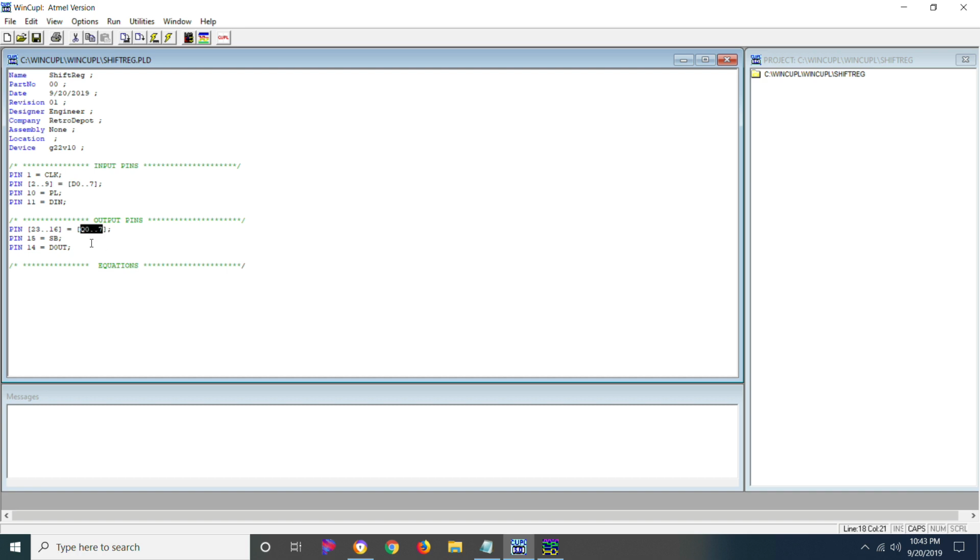Even if you decided not to do it that way and you were just going to be cycling this by hand, for example, to emulate a 74LS166 or a 74LS165, you could simply use the chip select as both a writing mechanism and a clocking mechanism. That's a pretty easy way of going about it. So we're not going to concern ourselves too much with that today. That's getting into circuit design and timing, and that's not really applicable when it comes to just writing the shift register. But on pin 1, we are going to have a clock.